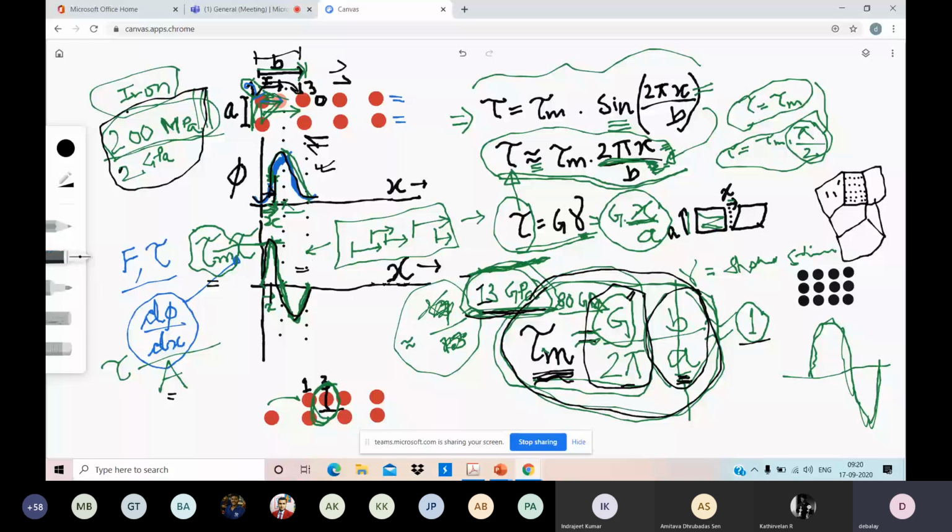And when you apply stress, you need not create a dislocation. This is what I showed, is this atom coming here because of the creation of a dislocation? Already there will be something like this. So there you need to apply stress sufficiently high so that this dislocation can move. And as the dislocation moves, a step will be produced here. That's why at a much lower applied stress, you see your yielding takes place. So this concept is very important.